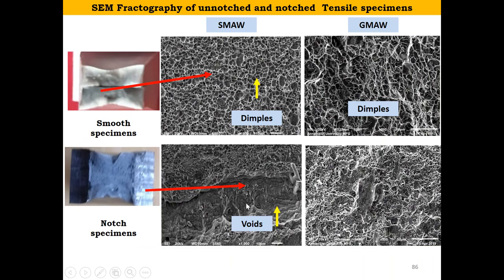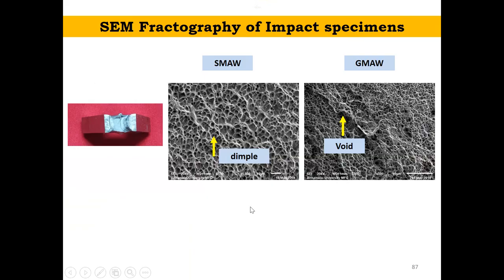For the notched specimen, we have observed voids in the middle. In the fractography of the impact specimen, dimples and voids were observed.